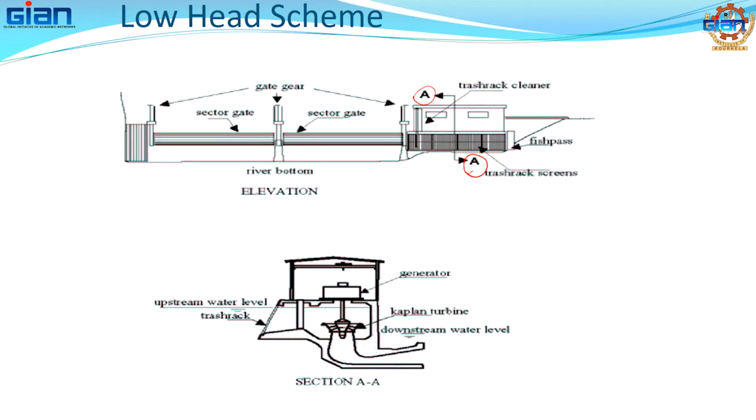But due to this particular arrangement, they have opted for a vertical axis configuration. The generator is up here, so the axis is here, right. So, this is the axis. So, this is a Kaplan turbine. Water comes through the trash rack, enters here in this chamber and then goes through the turbine. Turbine blades are here, right, and water goes out to the tail race, right. So, Kaplan is one version of reaction turbines. They can be used in any suitable configuration.